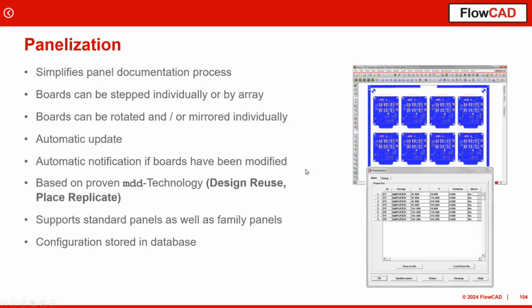Say you have opened a board database, or your single board, and then you're launching manufacturer fab panelization. Then you get an error, and the application is telling you, hey, a starter panel database must not include any part logic, no net logic. You should start with a board containing only 2 layers. It must contain a board outline and a route keep in and a route keep out, and then you can open that database and start creating the panel from this panel starter base. This was a little bit awkward and confusing customers.